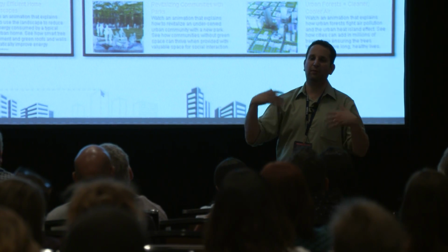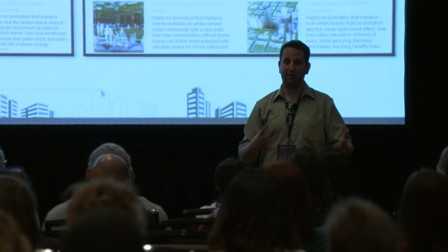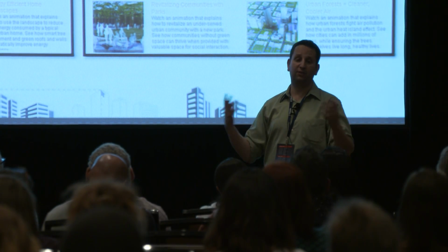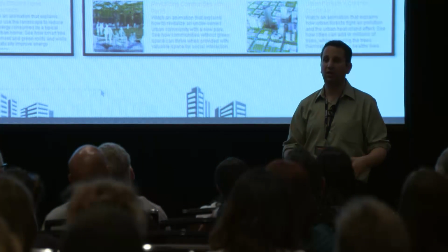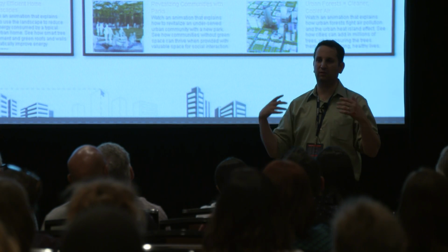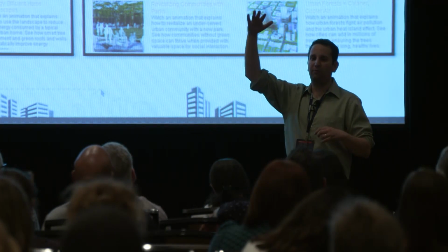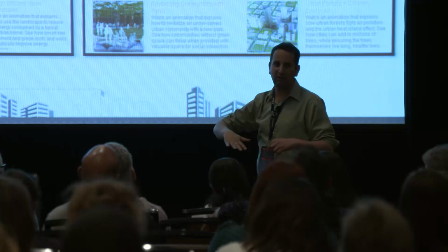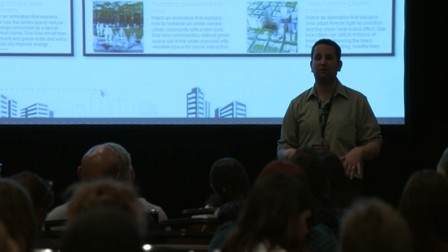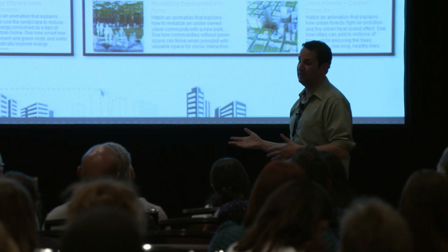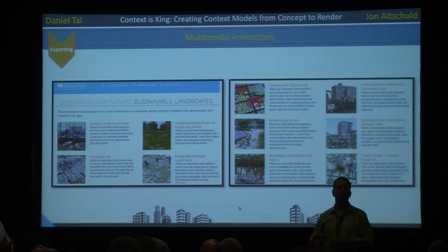So the question is, if we're working on a building, do we eliminate the interior, all the structural? I get a lot of Revit models. What we have to do, because they're so detailed, because they're really intended for construction, we strip it out. And the way to do that, there's a tool called Cleanup 3. Anybody use Cleanup 3? Good tool. And then hopefully it's all layered correctly, and we can go in there and strip it out. So we do take time to reduce it for exterior modeling. I just recently did a project where we had to keep everything, exterior and interior, which made it challenging in terms of how to do it. Ken?